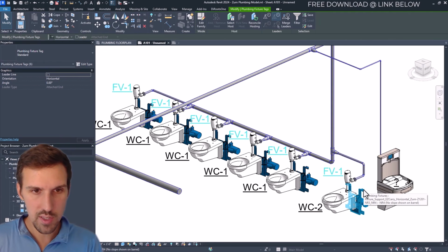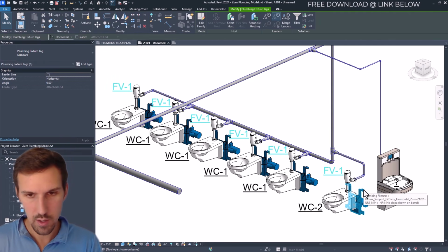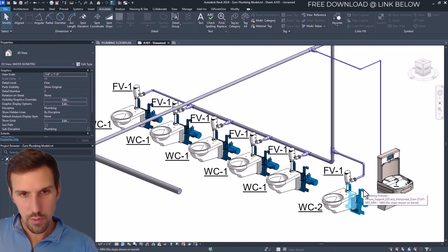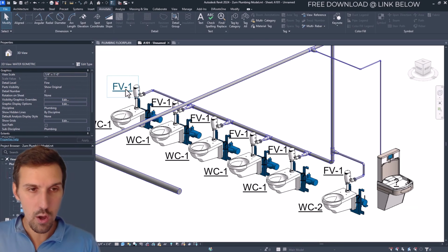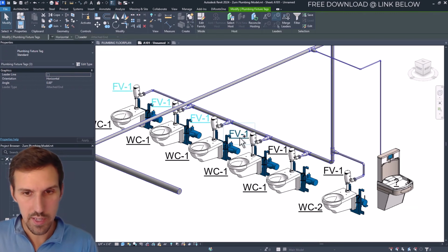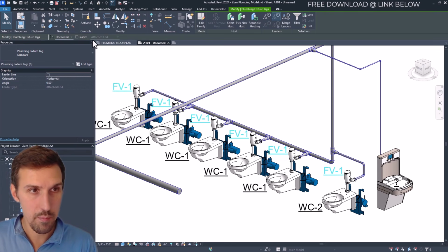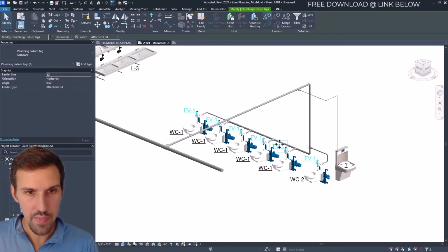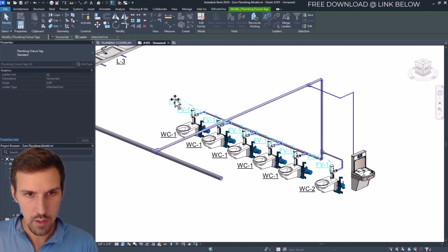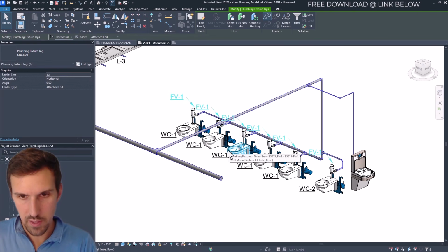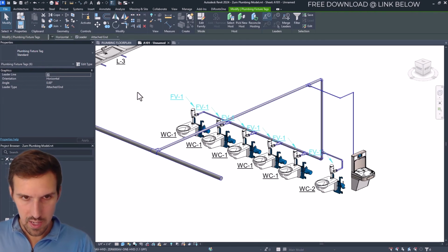We could also use the typical process for up here, but I'm not going to do it. So those are right there. Or we could also just make all of these leader type tags. So let's click on all of them. Let's click up on leader, and then let's move them at the same time. And you're going to notice they kind of all move into the same spot, but that's not looking great. I don't love the way that looks.